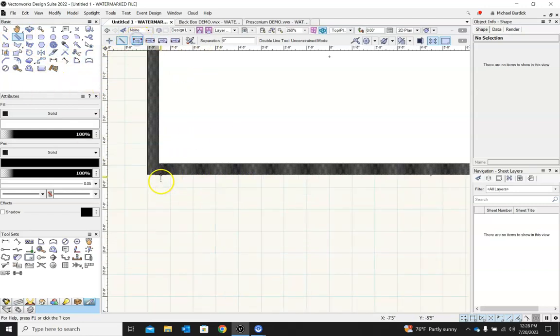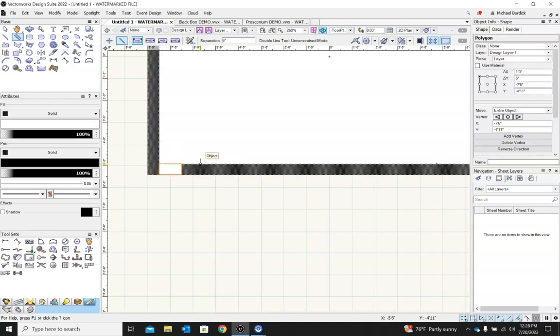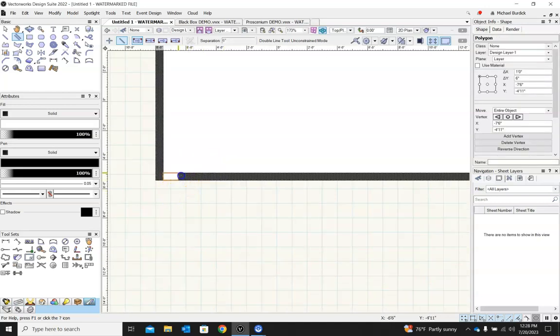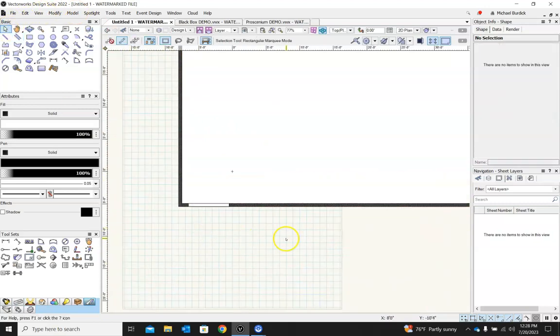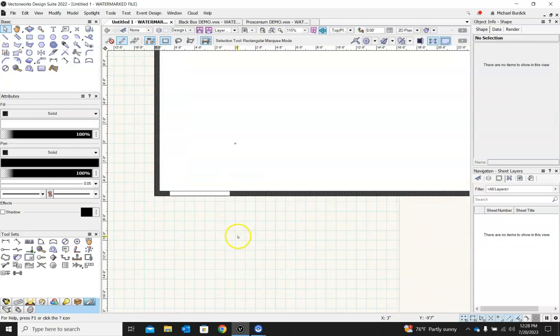I know that it starts 1 foot over here, so I'll just draw a double line there, tab 1 foot. So that puts me a foot away, and then I know that this door is actually 6 foot long, tab 6 foot. There we go. And then I'll just get rid of this dummy. So now I know that's where that door goes.